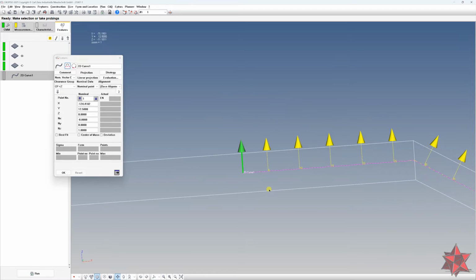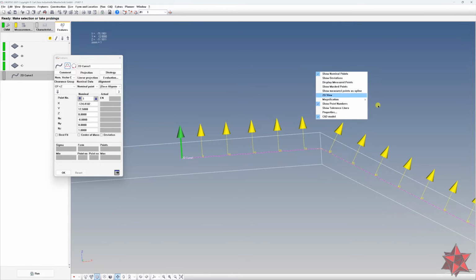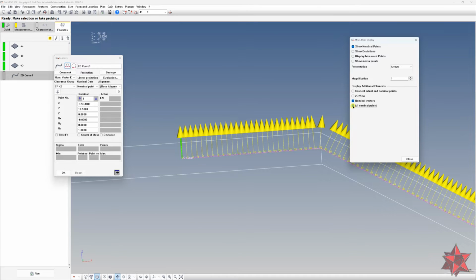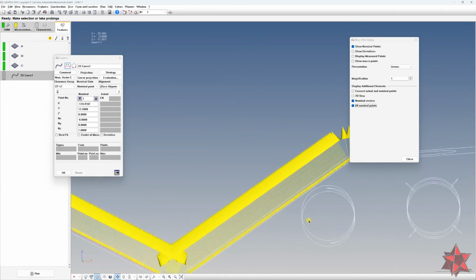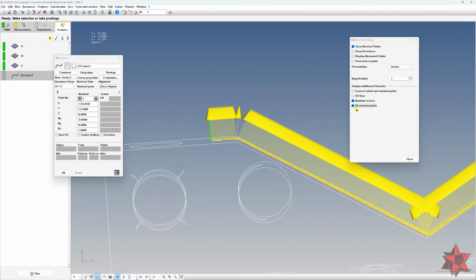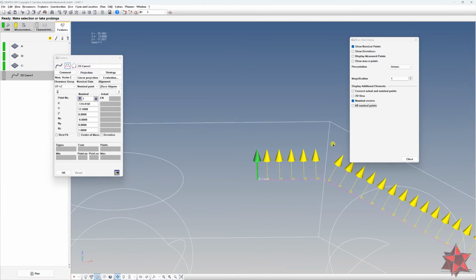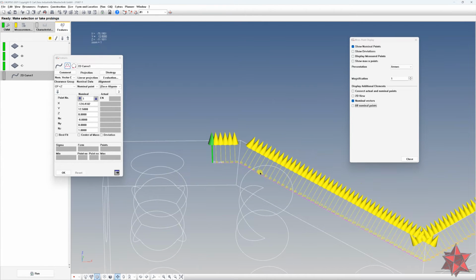And under magnification you can show the point numbers, and here we can see that actually the point numbers are from 5 to 5. So it's 1, 5, 10, 15, 20 and so on. But we can also show all the points. Go to properties, and here we can check this, all nominal points. And now we have all 500 points right here. But I do recommend that all nominal points should not be checked in order for the software to not be constrained of too many information.